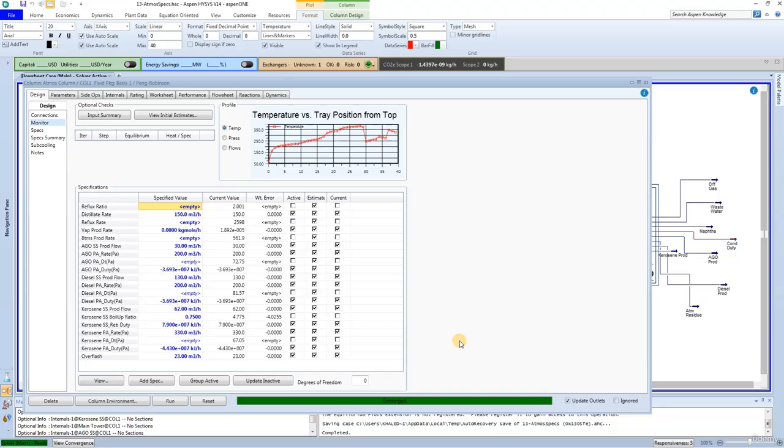Now to task 4, product stream analysis and cut point specs. The atmospheric column is now being solved using product flow rate specifications. Flow rate specifications are probably the easiest to understand conceptually. However, they are also the most inflexible way of defining the column. If the feed flow rate were to change substantially, for example, the column may fail to converge because the material balance couldn't be closed.